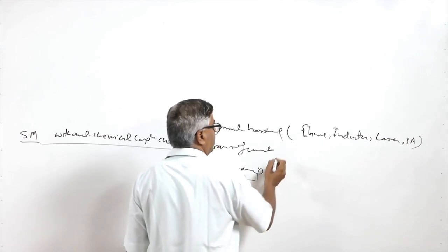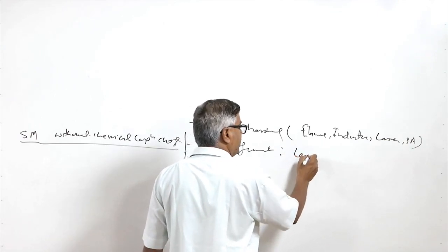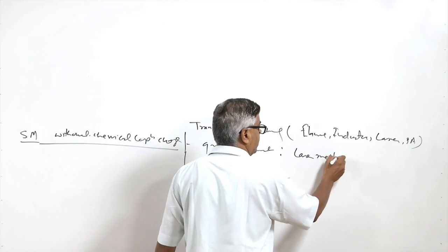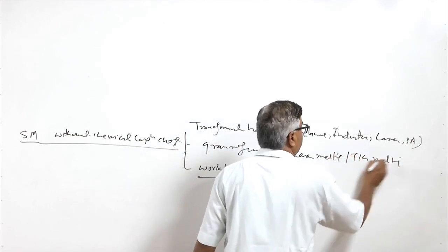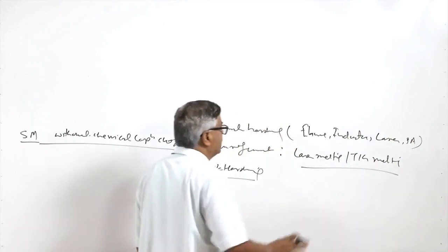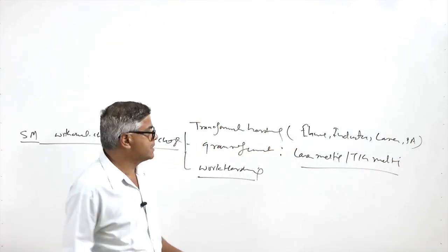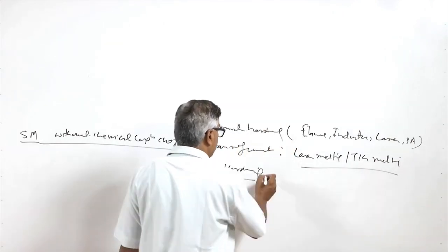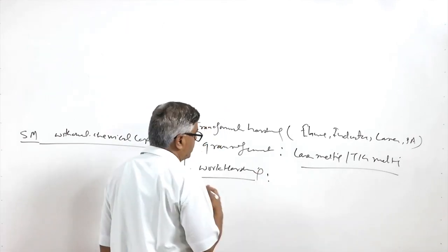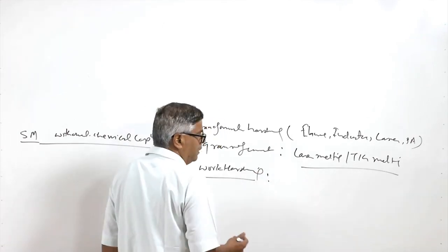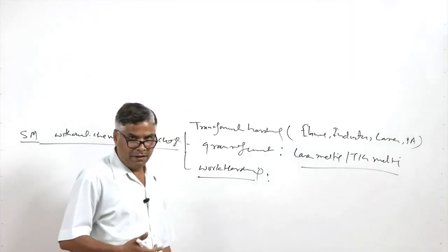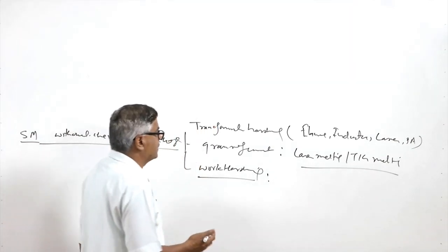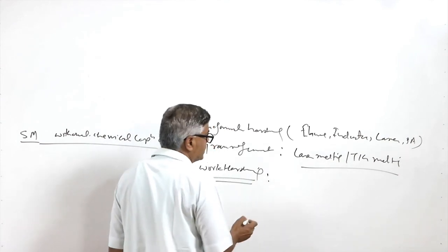For grain refinement, laser melting or TIG melting can be used. TIG or PAW melting can be used for refining the grain structure, especially of substrates having a coarser grain structure. And the processes which work on work hardening, where near surface layers are deformed plastically, facilitate improvement in strength and hardness, and so the wear resistance.